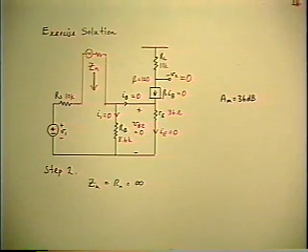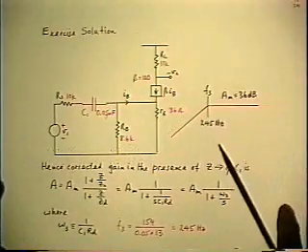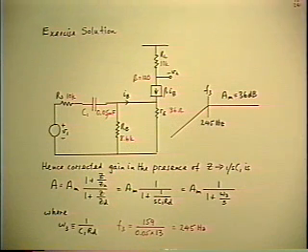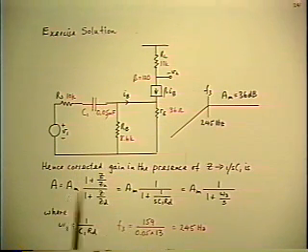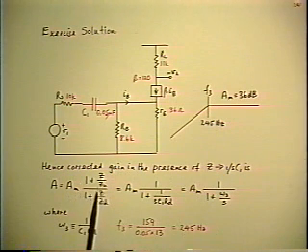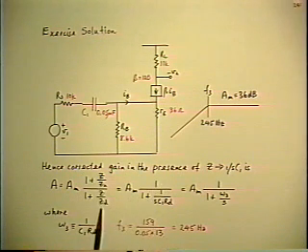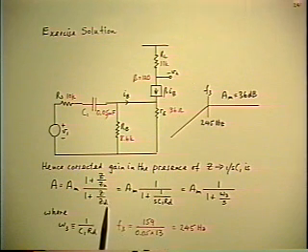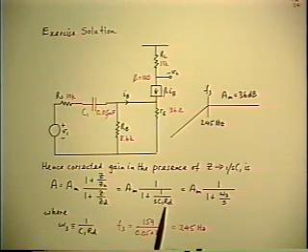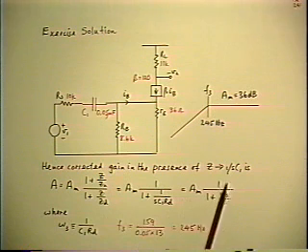So now we have both the RD and the Rn. And the last step is to put the extra element in there, which is a capacitor. And the series form of the theorem says the gain in the presence of the capacitor is the reference gain when it was an AC short, which is AM, multiplied by the series form of the correction factor, in which the Zn is infinite, so the numerator is 1. And in the denominator, Z is 1 over SC1, and ZD is RD, which we calculated. So you get an inverted pole due to the capacitor, and no 0.